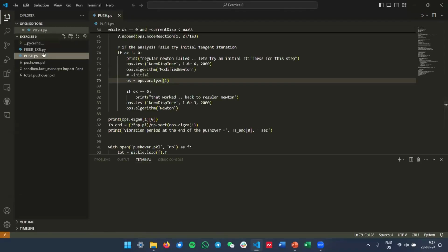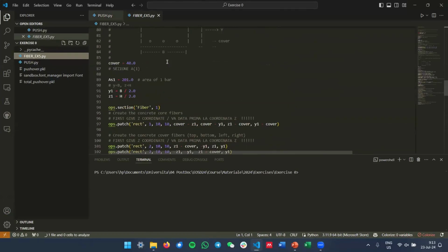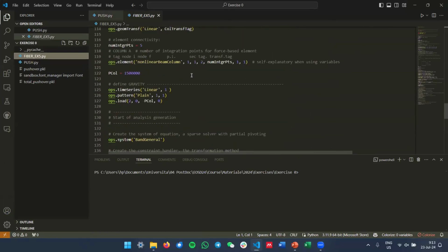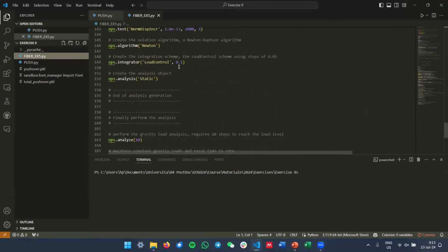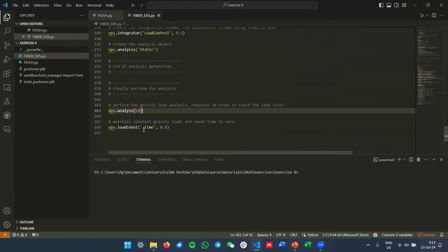Let's go back here. That is the simplest. With just OpenSees, I declare everything of the structure: geometry, materials, sections, stuff like that, and then run gravitational analysis. Gravity loads, yes. Depending on your structure, typically for civil structures, you apply gravity loads and then you run eigenvalue analysis. Can it produce nonlinear also? Typically, no. But it depends on the type of structure that you're analyzing.